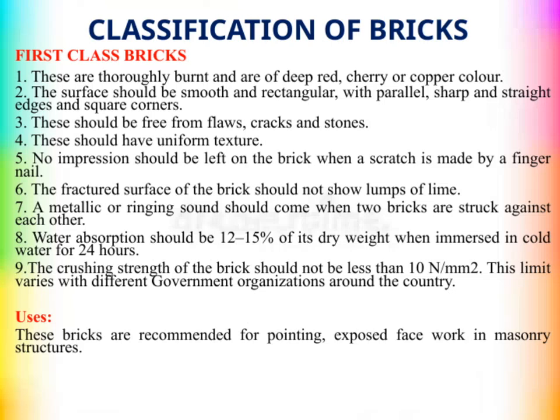Let's take a closer look at first-class bricks. These are thoroughly burnt, which gives them a deep red, cherry, or copper color. The key here is that they are well fired, ensuring durability. The surface of these bricks should be smooth, with a rectangular shape, featuring sharp, straight edges and perfect square corners. This uniformity helps in achieving a neat and stable masonry work.